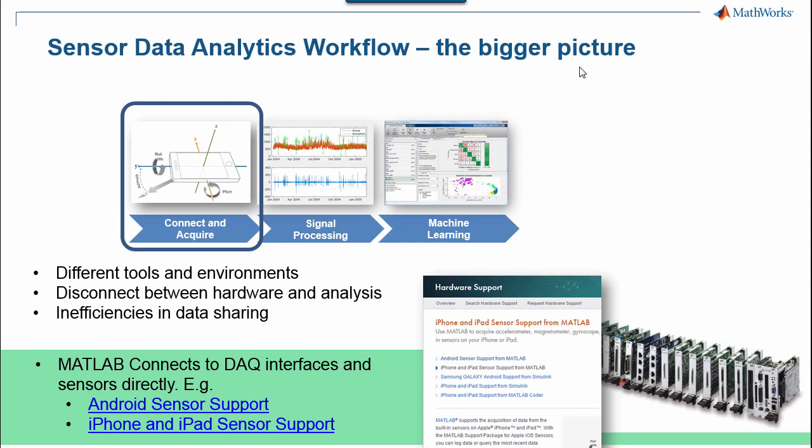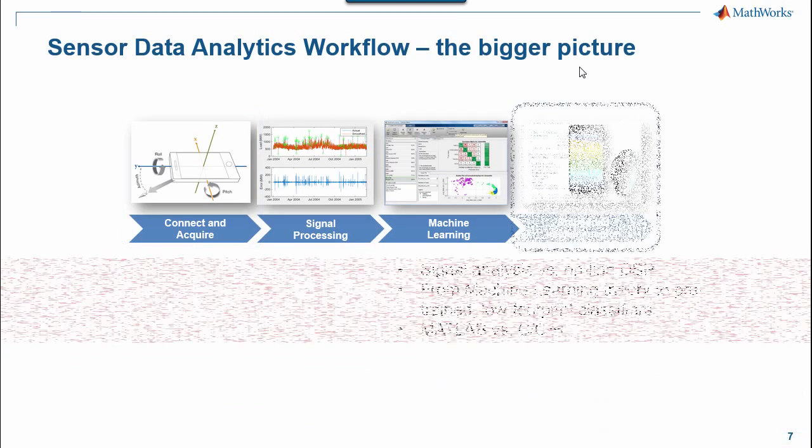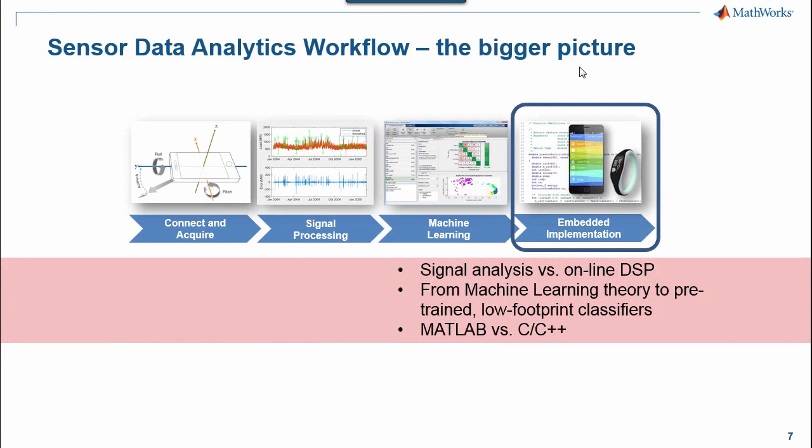Now, thinking about the end of a development workflow, imagine that your shiny MATLAB algorithm had to be implemented on a real-time system, for example, on an embedded device close to the accelerometer itself. In this case, not only will the final real-time software probably have to be rewritten in C or C++, but the actual functionality of the algorithm would have to be readapted in the final product. The machine learning portion would probably need to be simpler.